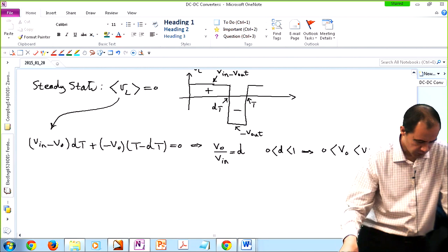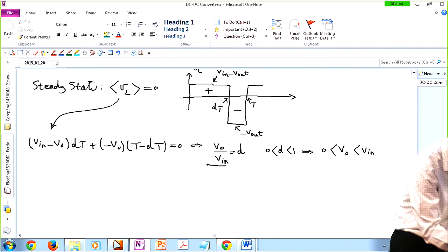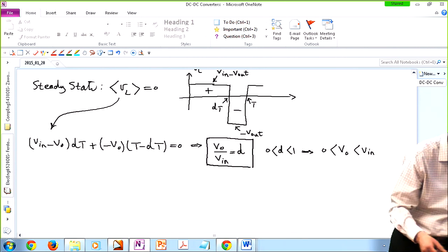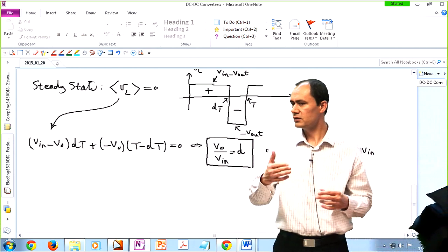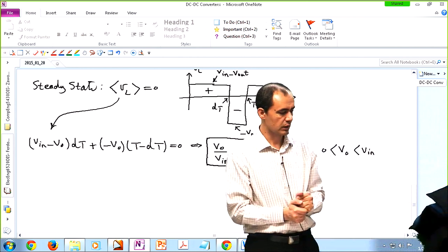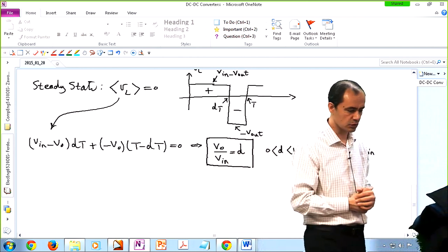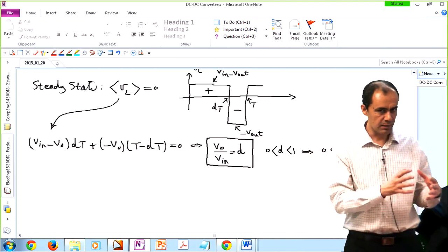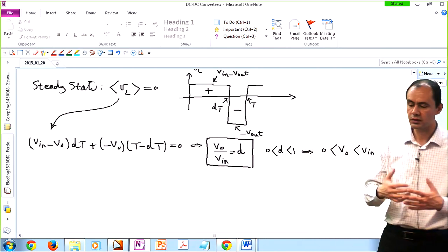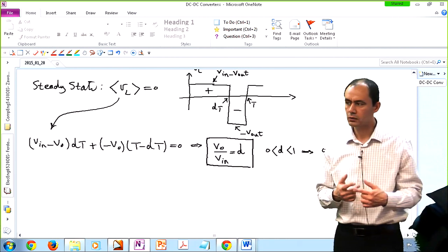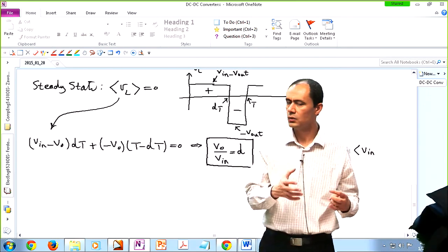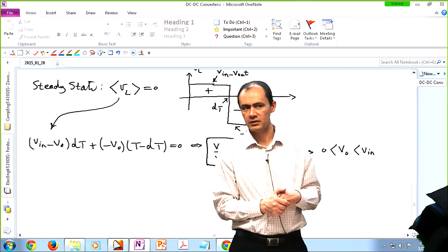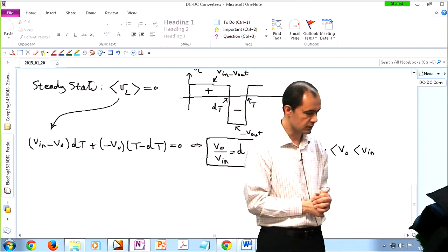Okay, so this is the voltage transfer ratio. Some people call this a DC transformer because it is like a transformer with a turns ratio of 1 to D, and it is actually converting one form of DC signal to another one. So the laptop example that we were talking about earlier: the battery of the laptop is, for instance, 20 volts, but the CPU consumes, for instance, 3 volts. So probably there is at least one or several stages of buck converter in that laptop.